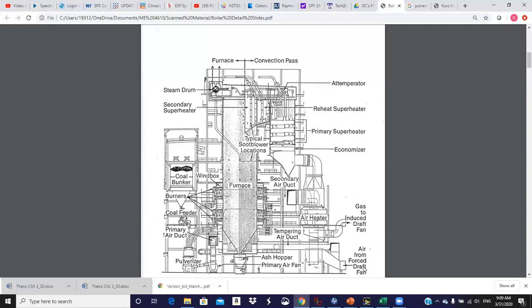Each unit at Kingston, there's 9 units. Each unit has its own coal bunker, and there's a conveyor up there that can fill each of those bunkers with probably 2 days worth of coal supply. And so they try to keep those bunkers appropriately filled. The coal then falls down from the bunker, and they typically have scales that will weigh this coal, and then it fills up as we need to supply coal to the pulverizers.